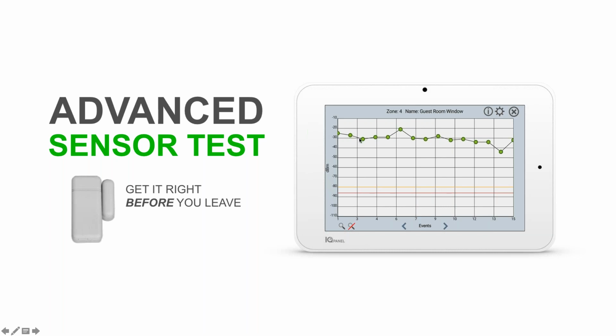So every time that sensor talks, every time you open a door sensor, it's going to log a dBm point on this graph. And you can see how strongly that sensor is communicating, right? The cool thing about this test is it's extremely sensitive. You can move a sensor from a wood door to a metal door and watch these dBm levels get worse, right? Just really cool, the granularity that you get with this test.